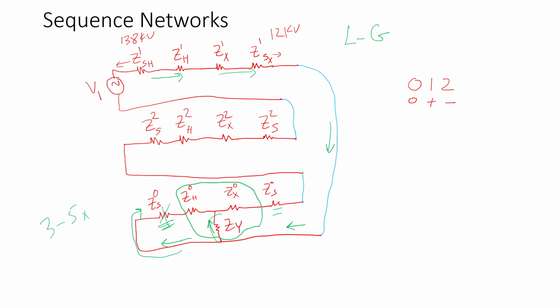So basically, I showed the sequence components, positive sequence, negative sequence, then zero sequence, and how important the T model is, and also including the system impedances, especially for the calculation of the line to ground faults that the main windings will see, as well as the stabilizer winding.